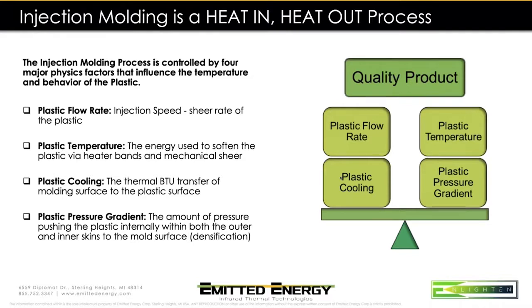And those different types of mechanical shears are all conducive to how well your material is formulated from your material supplier. In this, they put a lot of what we call heat stabilizers, or bodyguards, as they say, for the molecular chains, flow plasticizers and those types of things, and then fillers, and you have all types of stiffeners and talc that will be in there. And all those will affect all these different, what we call 4 horsemen of the apocalypse.